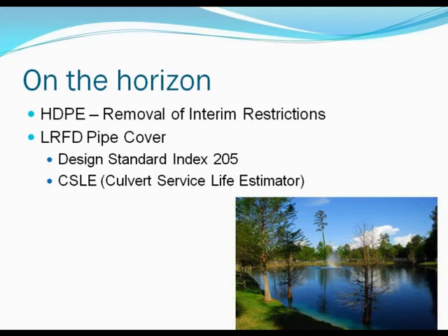And on the horizon, in fact, this one has already happened. The removal of interim restrictions from HDPE pipe has been enacted as of Monday, I believe it was. And this is the result of years and years, goodness, maybe even a decade worth of testing, where we carefully examined the long-term properties of the polyethylene pipe. And a whole lot of research on this, and so those interim restrictions are removed.